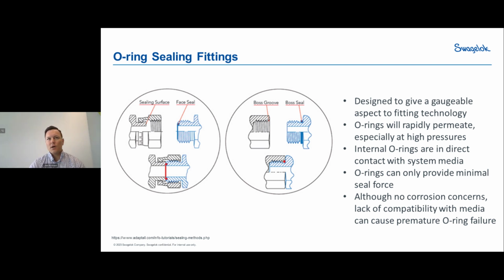O-rings also will not generate a high degree of sealing force. They deform rather easily, but that can be an issue at much higher pressures, right? You can't expect an O-ring to deal with the types of stresses that you would expect from some other technologies.